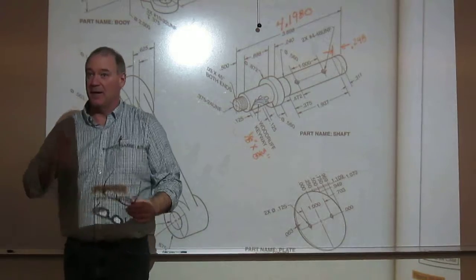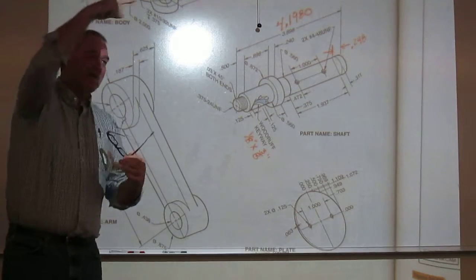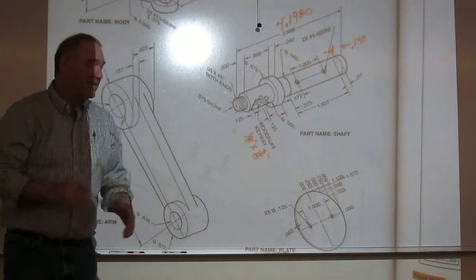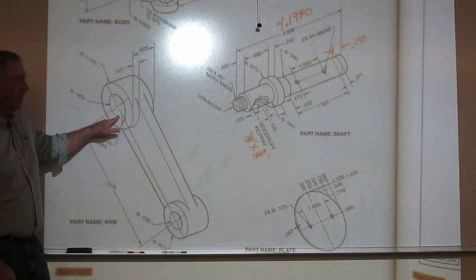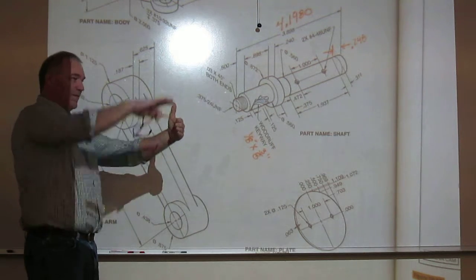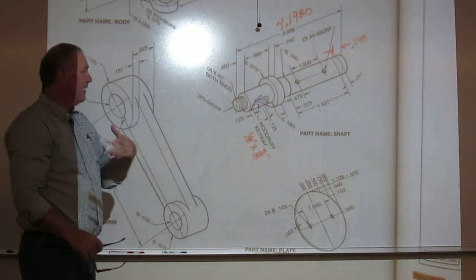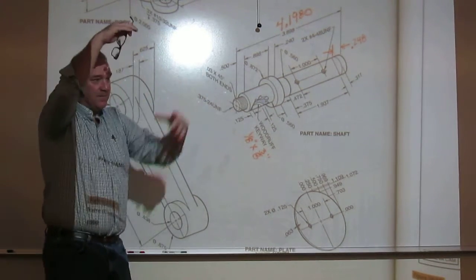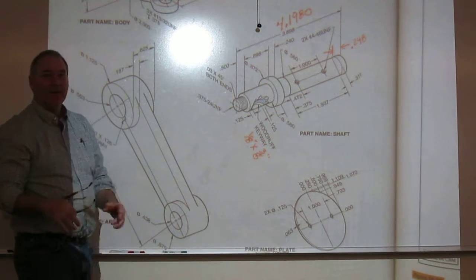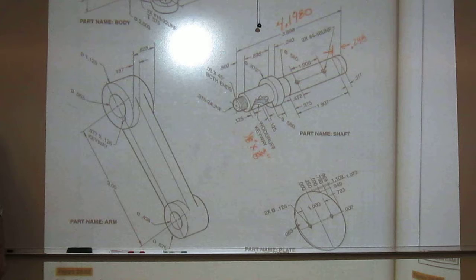How many times have you seen a valve like this with a big arrow on it that says off this way, on this way? That's exactly what's going on, because I'm going to put this handle on. When this is mounted, it's sitting there facing the user, and the handle's here in an off position. I rotate it to here to an on position. So I'm making it good for the user. And that's all lined up inside the body, perpendicular to the flow. Now you're starting to get into the operation of this, and you can start making design criteria calls on how you want this thing to perform.